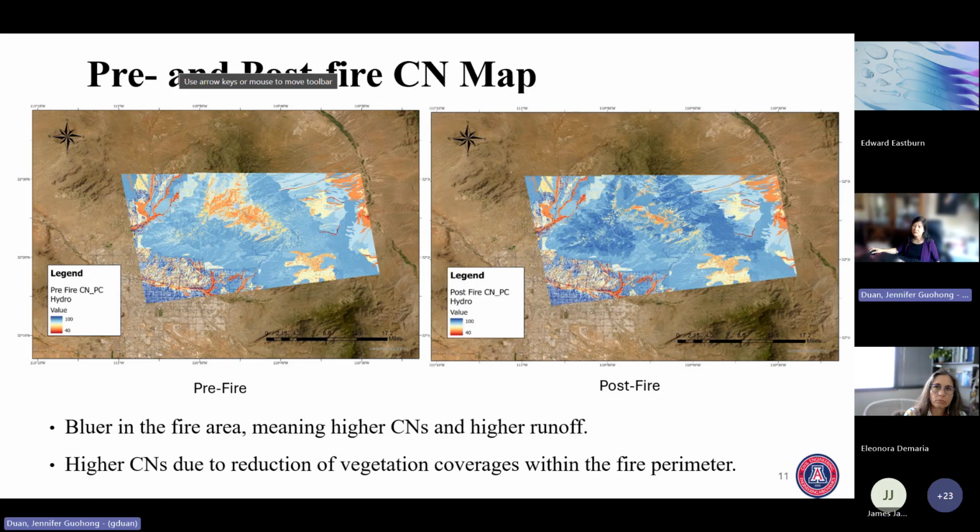We don't have that. We didn't do this study. This project ended 2 years ago, in 2022, because it was just post a fire and the county needed to know how much increase of runoff. And we did a study. We don't have the current situation after this 4 years of recovery and what the current vegetation situation is. It must be smaller than this. How much smaller, I don't know. I need to see the new vegetation map, and we can regenerate this curve number.